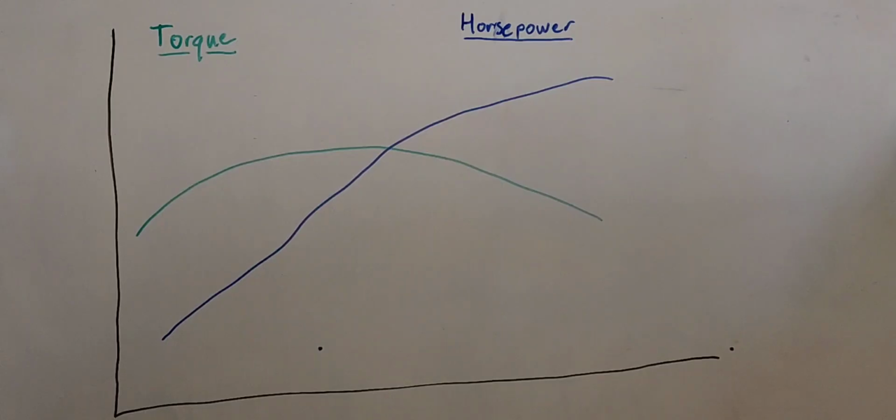We now get to the final piece that I wish to teach, and that is reading the dyno graph that you were given. Now, in this example, I'm not putting up numbers, but it's just merely looking at the curves. We all know that the crossover point is 5252 RPM, so in this case, that'll be where the two lines cross. So that's your RPM point. Horsepower and torque are going to be the same, so naturally they're going to cross there.